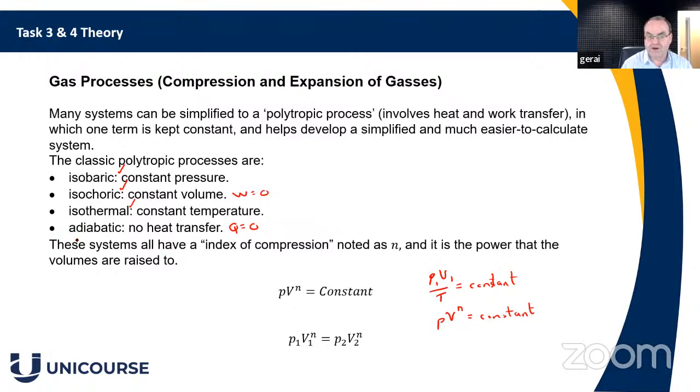Very important though, adiabatic process. If you have a petrol engine or a diesel engine and you have a compression stroke that compresses either the air in a diesel engine or the mixture in the petrol engine, then that process happens very quickly, and it's very, very close to being an adiabatic process, where there's no heat transfer during that compression process.